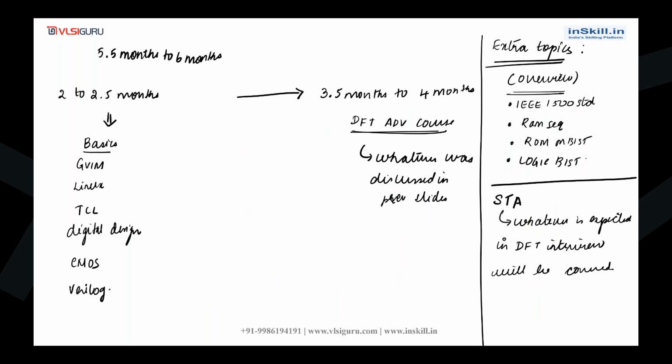For example, what is setup time, what is hold time, what is setup violation, what is hold violation, which one is more critical, setup time or hold time, why it is more critical, and how to find the maximum frequency of operation of a circuit. Some basic things expected in a DFT interview will be covered. STA is not a DFT topic, but some interviewers expect basic knowledge of it. These are the extra topics I will be covering apart from the course.